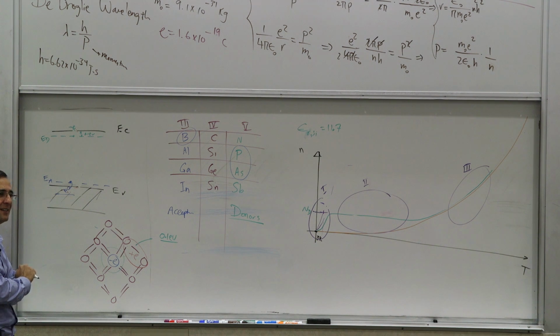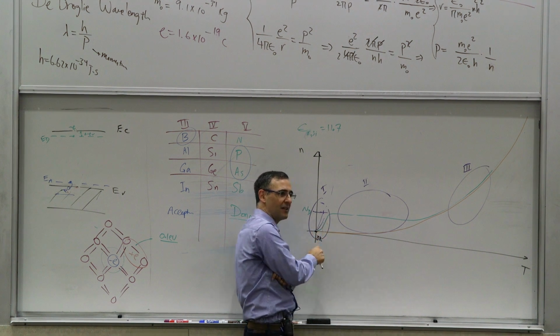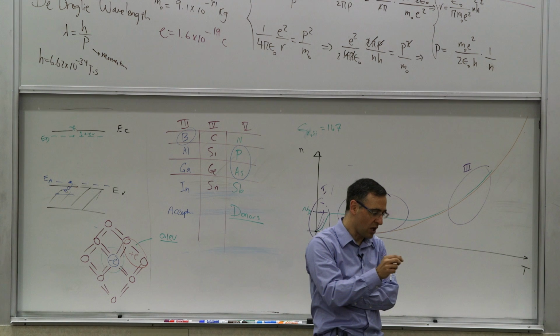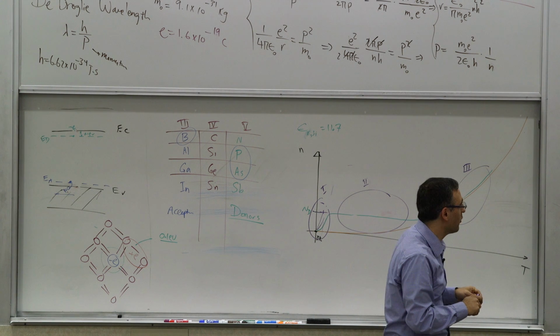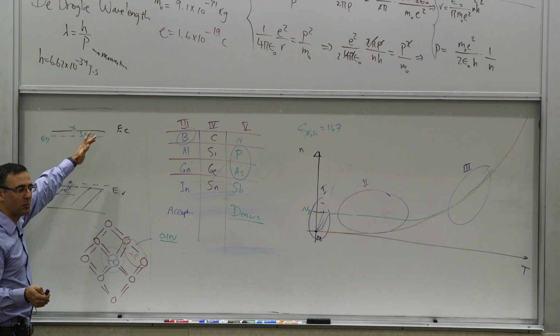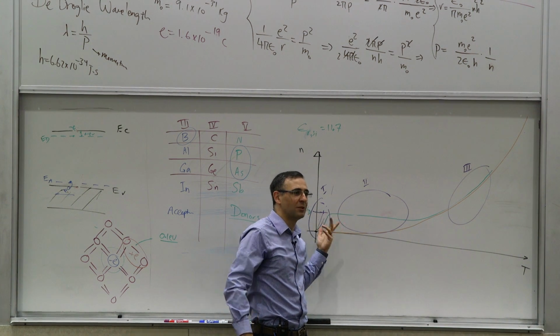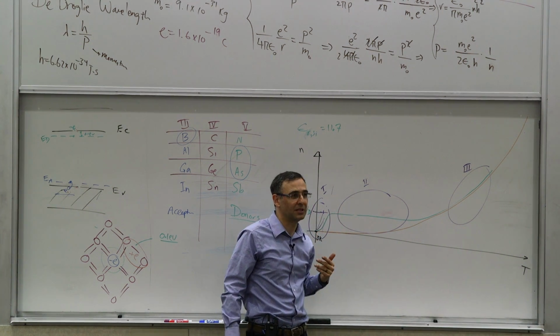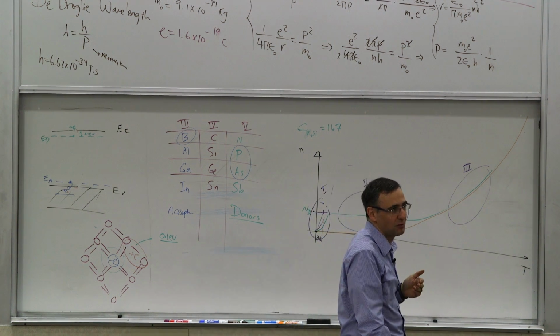Yes? Is there a good alternative to that if you're worried about temperature stability? Yeah, that's a great question. So that device would not be very temperature stable, because slight changes in temperature would change the number of carriers. So it can get thermal variation. The alternative to that is basically just use what you have, right? And also, there are certain types of semiconductor that create energy levels that are smaller. But if you're operating at very low temperature, let's say liquid nitrogen, I mean, liquid nitrogen is not that low, but liquid helium, not liquid hydrogen, liquid helium, then essentially you either have to overcompensate or live with what you have.